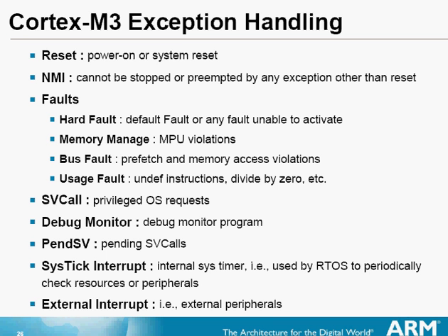Global interrupts enable and disable. During initial reset, NVIC is turned off. Therefore, the processor cannot receive any interrupt except for NMI, reset, and hard fault. To turn on interrupts with configurable priority, we write code like asm volatile CPSIE i. The CPSIE is an assembly instruction to enable the priority configurable interrupts. Actually, it is a shortcut to a longer procedure.